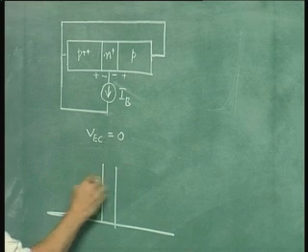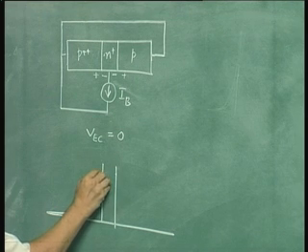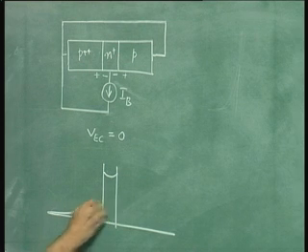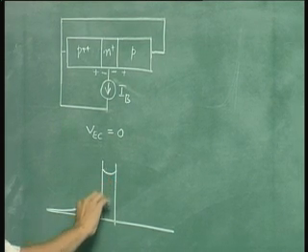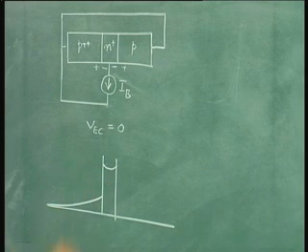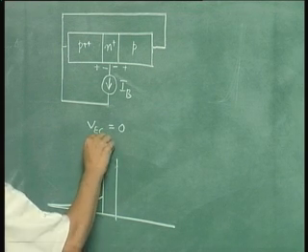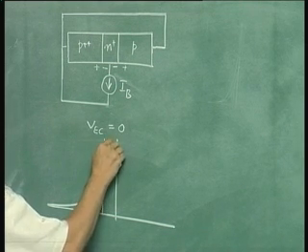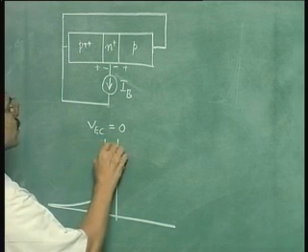So this means that from the diode theory, the boundary values of the excess carrier concentration would be the same at this end as well as at this end. So this is your excess carrier concentration in the base. Now please note that this value would be 10 times this value, because doping in the emitter is 10 times the doping in the base. So this is again not to scale. If I have to show it to scale, I must raise it up further, at least approximately to scale. So let us assume this is approximately 10 times, not exactly 10 times but approximately. So something like this.